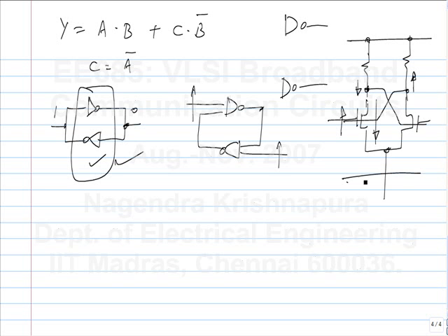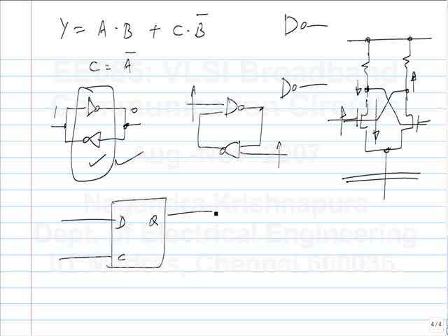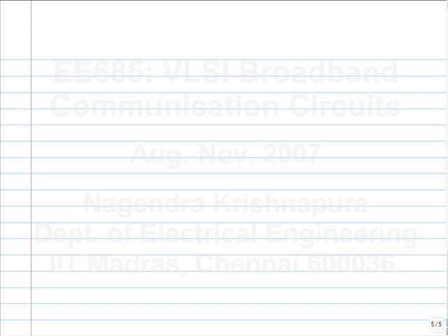So this is a latch, and what kind of latch do we want? When C has one polarity, we want this to go straight to the output. When C has the other polarity, we want it to hold the value that it had before. And this again is a multiplexer. Meaning in one of the phases D should go to the output, in the other phase Q should go into positive feedback. And since we have a multiplexer, we can make the latch quite easily.